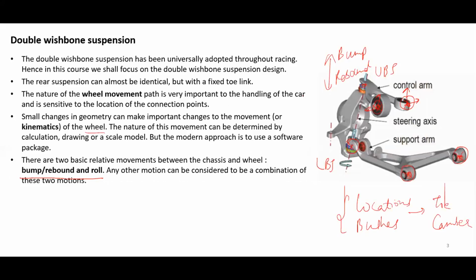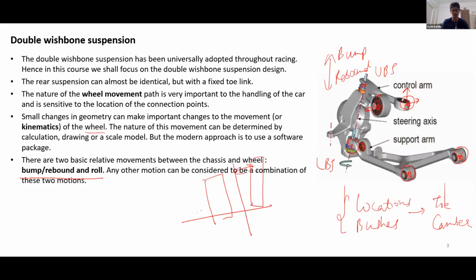Shailesh asks, during cornering, should we consider banking of roads or not? Absolutely, you should. All your angles are measured with respect to the road surface. So if your road is like this, then your camber angle is measured with the perpendicular to the road, right? So this becomes the perpendicular, and if your wheel is like this, so this becomes the angle.